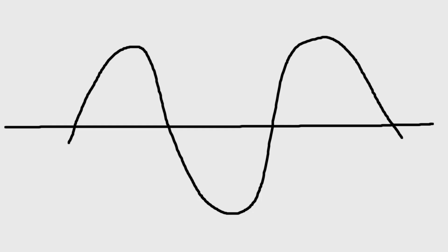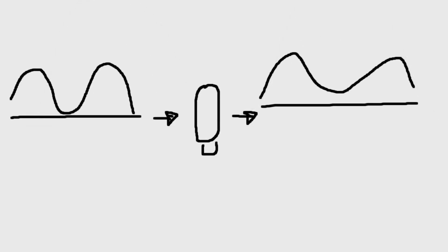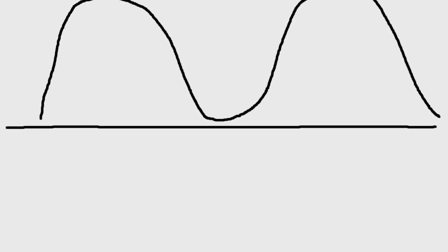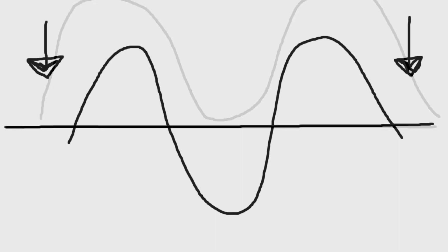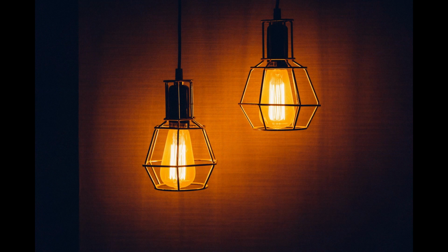Moving forward, we will now consider how the basic bias concept from the previous video relates to the concept of a load, with the tube's unipolar type conductivity and elements needing charge to non-zero voltages for operation, especially the plate needing a strong positive charge to attract the free-floating or negative space electrons in the vacuum. We need current to these elements to achieve that.